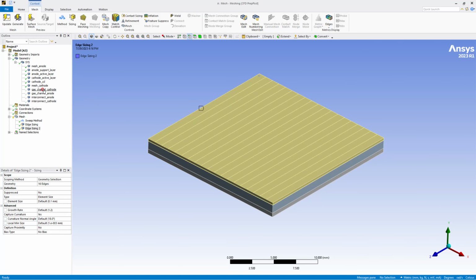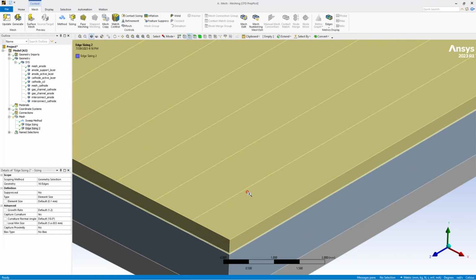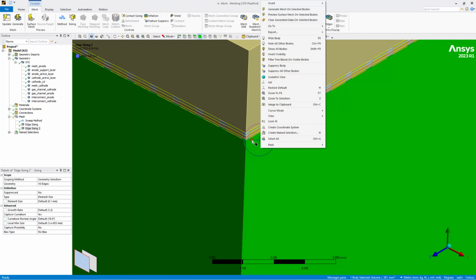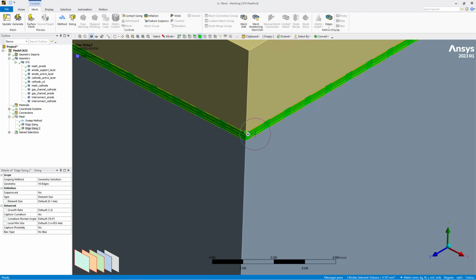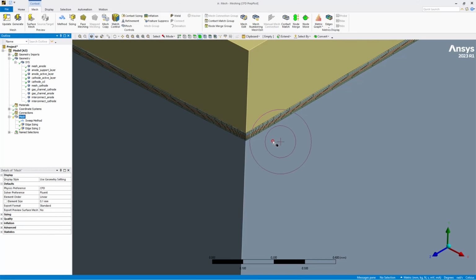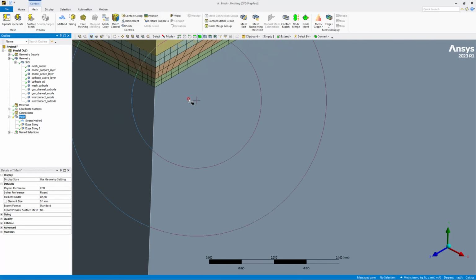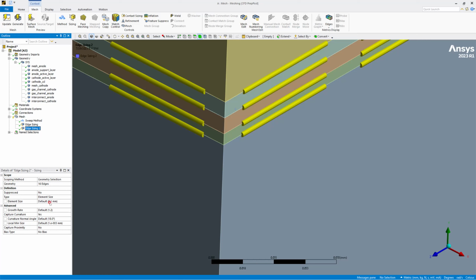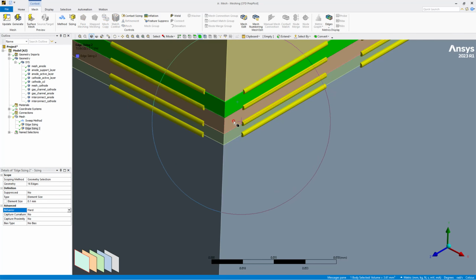So we should select the mesh node or the smallest layer, start with the meshing, and we'll go by body select, and let's select not this one, this body. These bodies are planar bodies, so it should be meshed with no problems. And if we click on the mesh, we will be able to see the mesh. But now you see there are too many distortions available. You can see many distortions, so I think we missed the hard setting, set the default to 0.1, and we need to set the curvature to no to make the behavior of the sizing as hard. And now we will mesh them again.